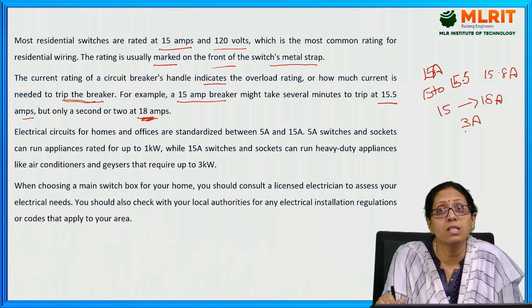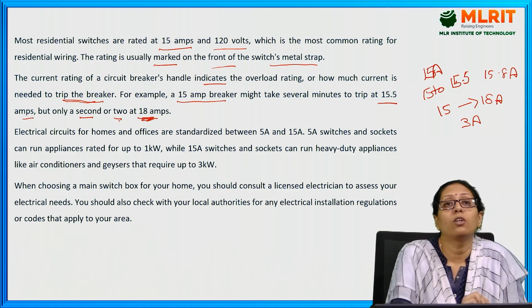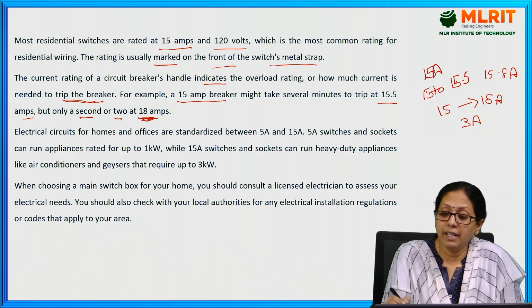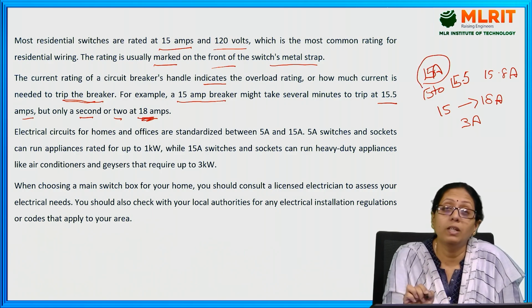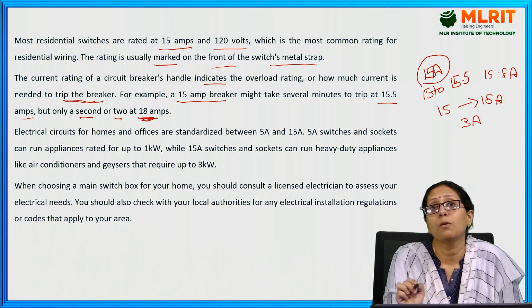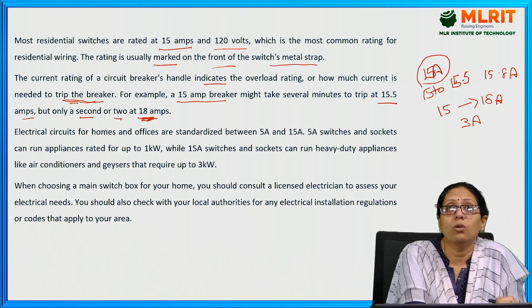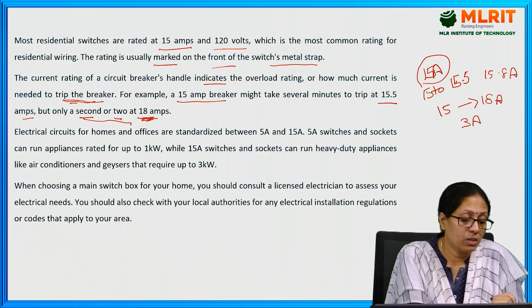So when the difference is more, it will take very little time, that is 1 to 2 seconds, to trip. So if the current is near the rated value, it will take a lot of time to trip, and if the current difference is more compared to the rating, it will take only 1 to 2 seconds to trip. Next one.